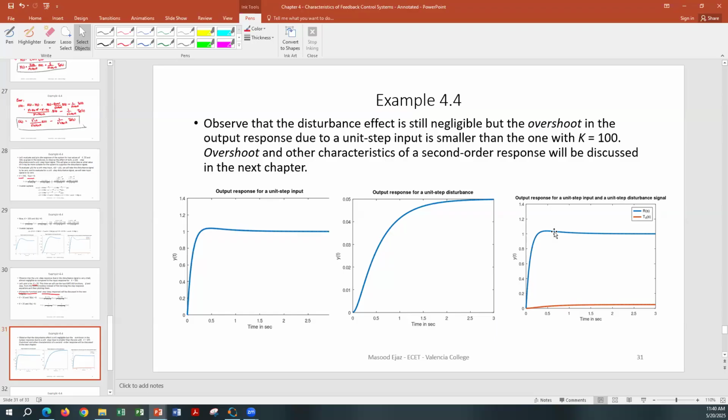Yeah, so overshoot, basically, remember, that's the output. If it is a mechanical arm, or the angle, but it's not a mechanical arm, it's the angle, right? So the angle is deviating before getting into line. The overshoot is going to be, it is deviating a lot at that time before it becomes a steady state, and error becomes 0 between the desired angle and the output. Because when output becomes 1 and the input is 1, the error becomes 0. But before it becomes 1, it is moving a lot if the overshoot is very high.